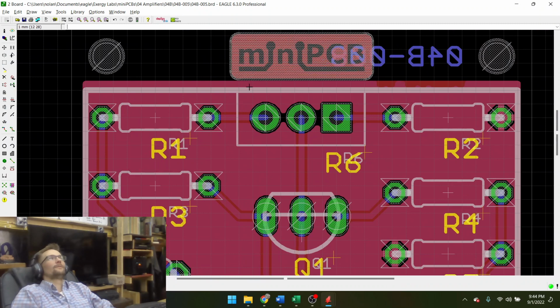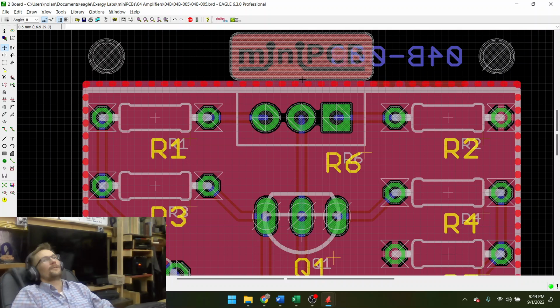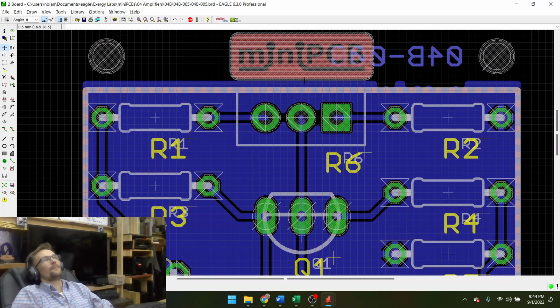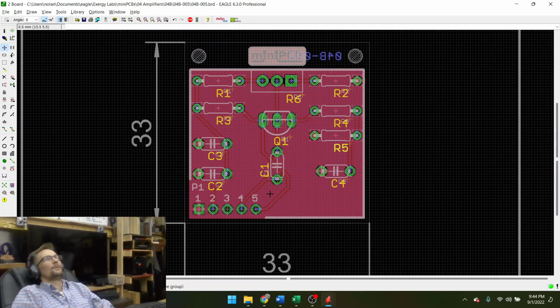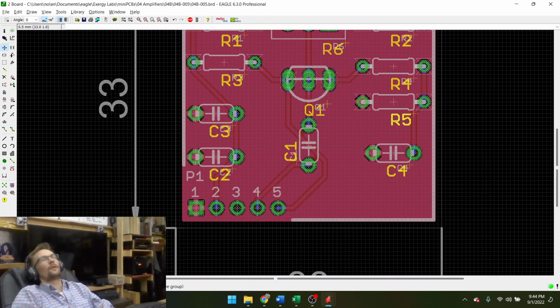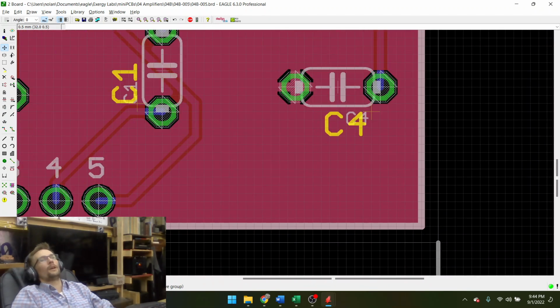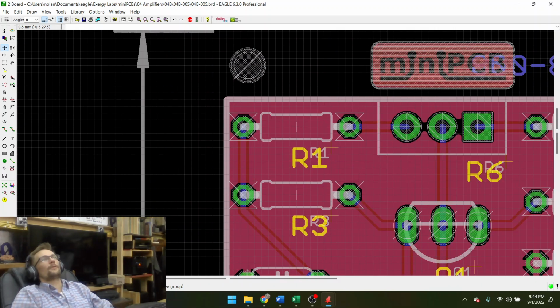So this is on a 1 millimeter grid. I need half. 0.5. Give me the border here. Move this guy. Yeah. Bam. On the bottom as well. Bam. Cool. So that now when I do my ground plane, I'll just copy the white line that I drew, and then I'll know that it's always good.